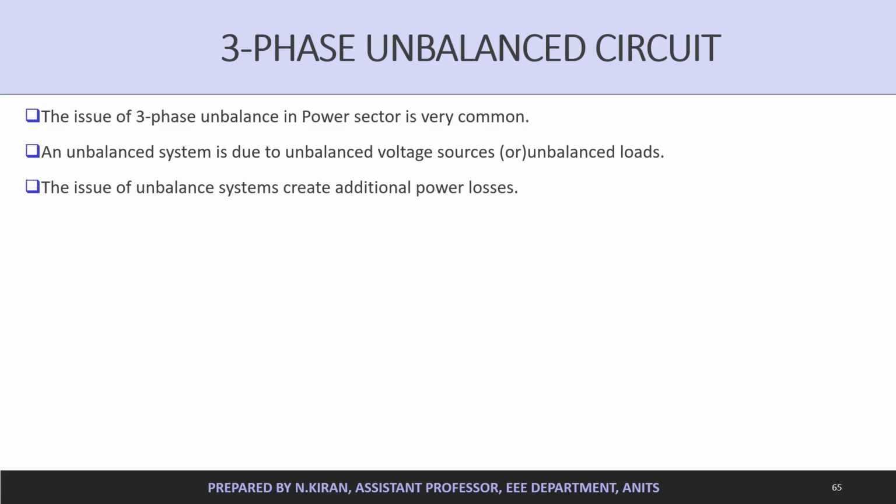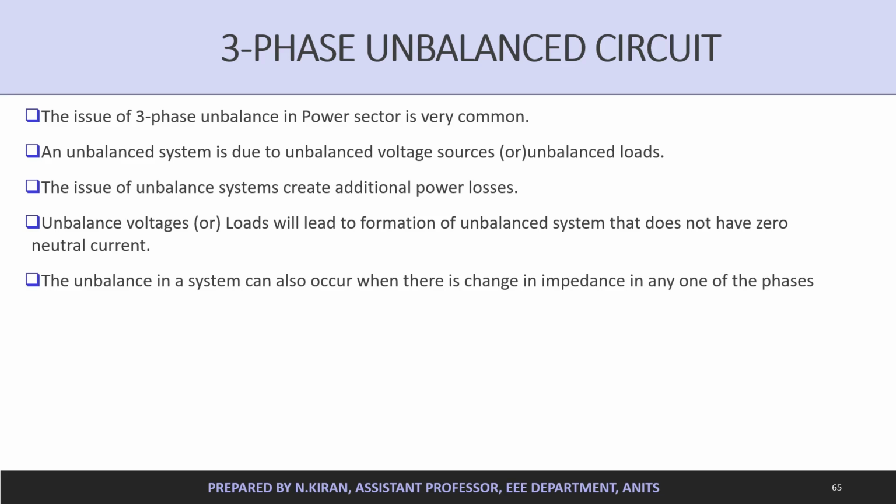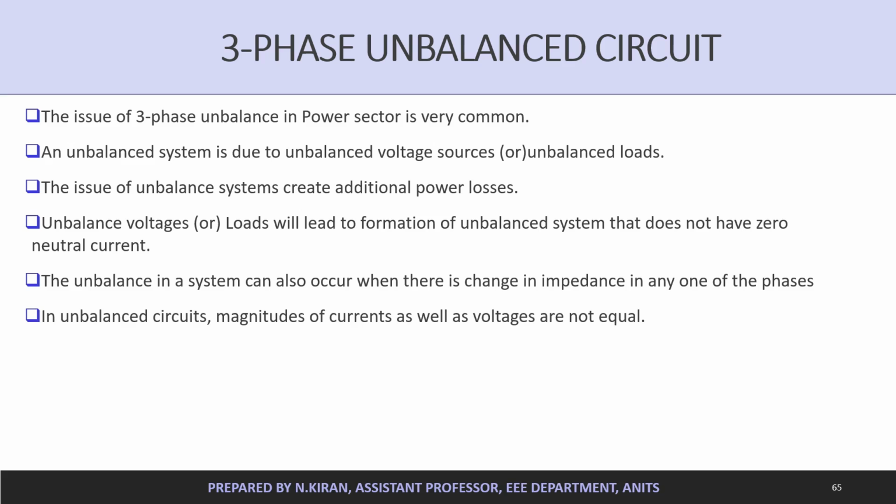The issue of unbalance creates additional power losses, and unbalanced voltages or unbalanced loads will ultimately lead to the formation of an unbalanced system. Thereby, the neutral current will no longer be zero. The unbalance in the system will also occur if there is any change in impedance in either of the phases.